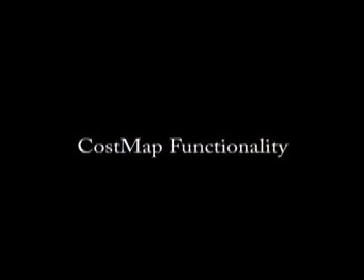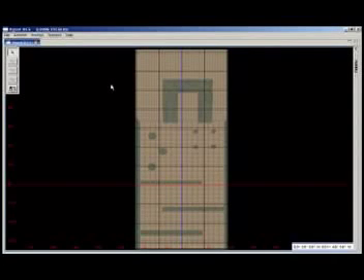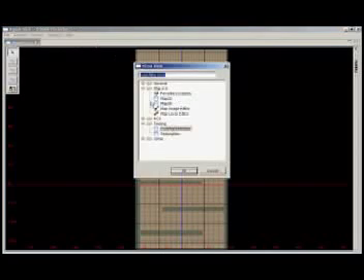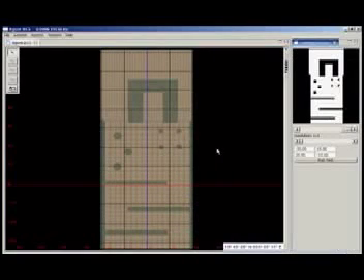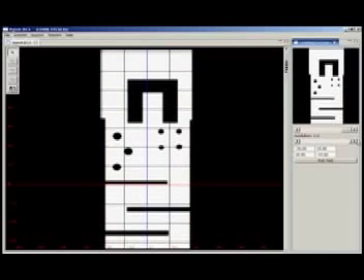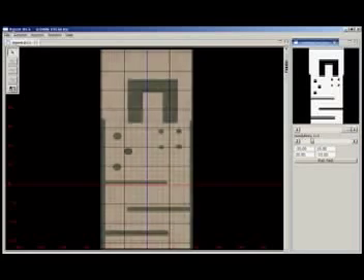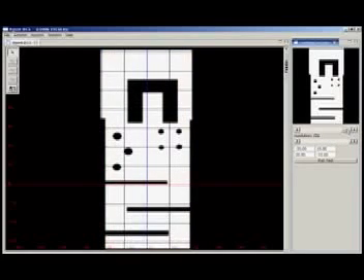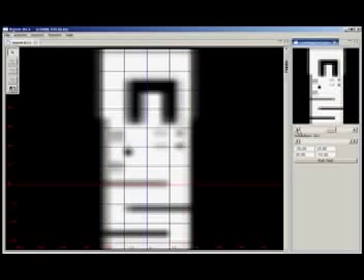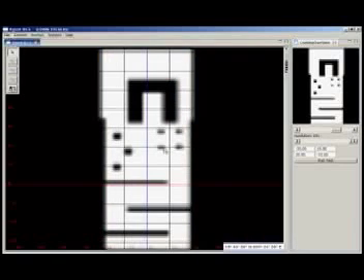To allow for a higher level of control, we implemented a multi-resolutional cost map structure into our application. This cost map is an internal representation of prior knowledge about the arena which is currently being used. The cost map allows for section-level agents to intelligently give routing information to the vehicles within the arena. The multi-resolutional aspect of the cost map allows for agents at different levels of control to see information that is pertinent to their level of detail. In short, the lower your level of control, the higher the resolution required to accomplish your goal.